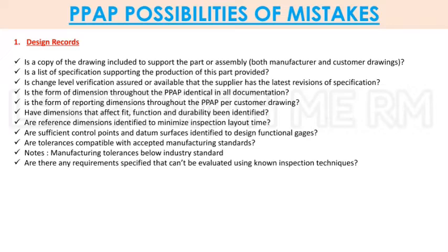Is the form of dimension throughout the PPAP identical in all documentation? Is the form of reporting dimensions throughout the PPAP per customer drawing? Have dimensions that affect fit, function and durability been identified? Are reference dimensions identified to minimize inspection layout time?